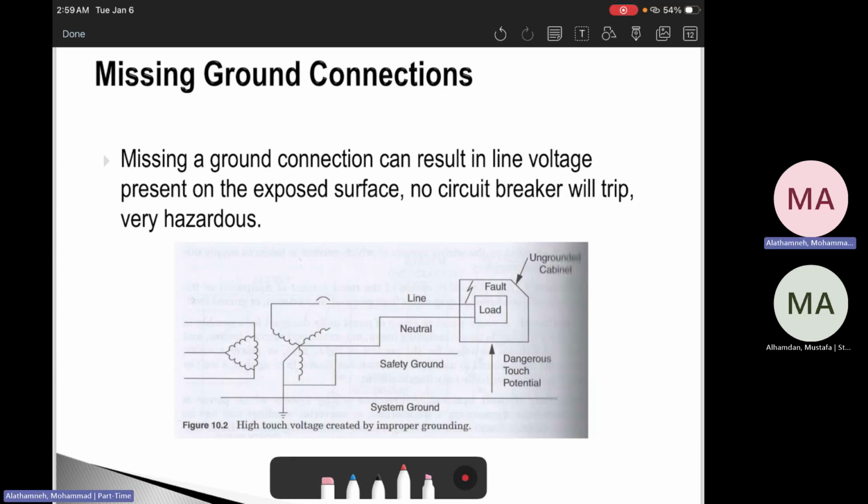So the ground rod alone does not guarantee a fast trip; the protective earth conductor and bonding are what create the low impedance return path. Again, some people just say let's put in the ground rod and that alone is sufficient, but no, just make sure the protective earth is working properly.